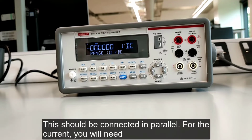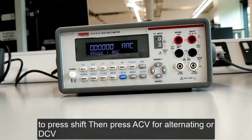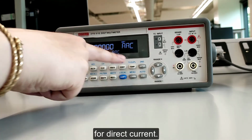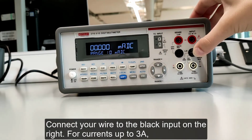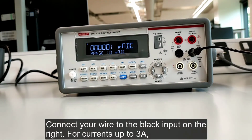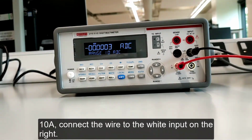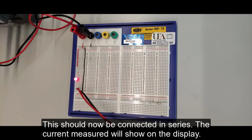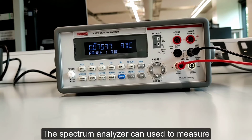For the current, you will need to press Shift, then press ACV for alternating current or DCV for direct current. Connect your wire to the black input on the right. For currents up to 3 amps, connect the wire to the white input on the left. For currents up to 10 amps, connect the wire to the white input on the right. This should now be connected in series. The current measured will show on the display.